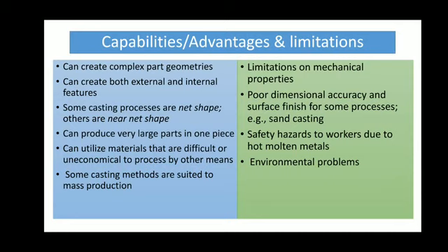That is net shape manufacturing. So it's possible to get the final required product in its exact dimensions with the help of this casting process, provided you carefully design the whole mold and the process is carefully executed. A very large size part can be manufactured in a single piece.